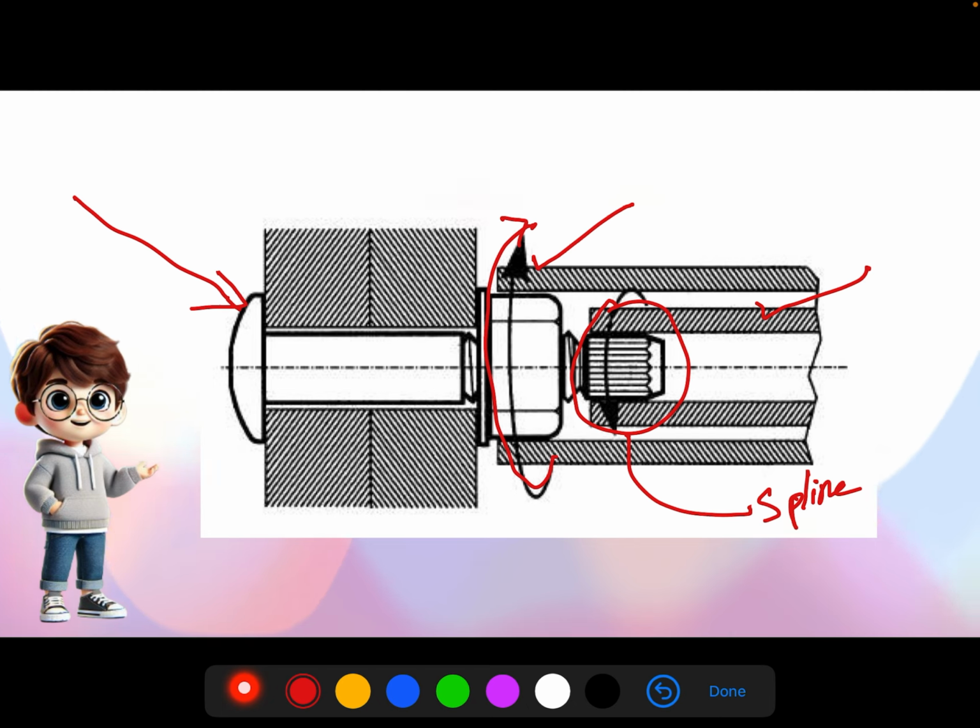Once the nut is completely rotated and the bolt achieves its full capacity, then this spline will rotate in the opposite direction. Then this spline will be twisting off. So this type of tightening is called twist off type TC bolt tightening. I'll share a video in the description below. In that animated video, it will show clearly how this twist off type tension control bolt tightening will work.